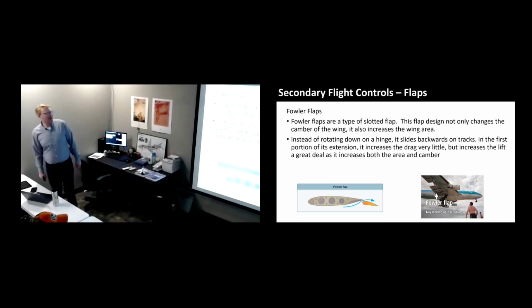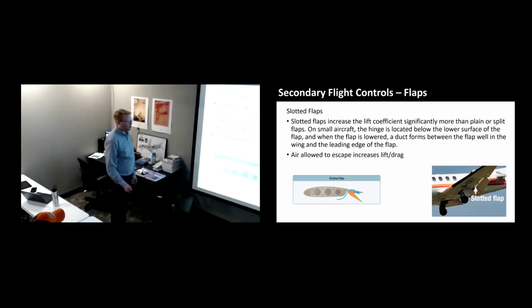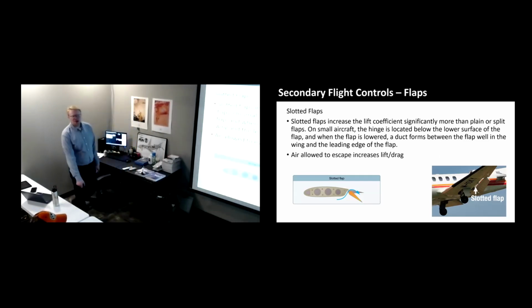Now, I didn't mention it so far, but most flaps are controlled either mechanically, electrically, or hydraulically. Like a Piper product, or most Piper aircraft you'll fly, they will be controlled with this little piece here. That will usually be mechanical. You move a handle in the cockpit and it just mechanically moves a couple of cables and linkages, and that's what causes it to move.